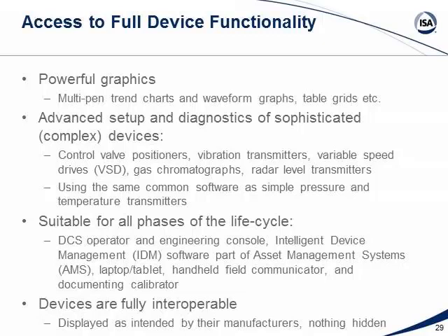But the nice thing about the FDT technology is it gave the device supplier full access. He could do anything. I mean, it literally is a Windows application. And that powerful part about FDT is that if you're writing a real Windows application, you've got full system control. You've got all kinds of advanced mathematics and functions, well beyond what EDDL could provide.